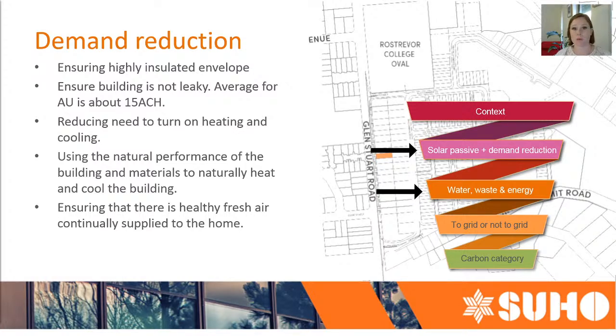If we discuss with you early on about air leakage, then we set those priorities in terms of how airtight the building is. So commonly you'll get leaking through certain parts of windows if they're not sealed correctly. Doors are a big one, garage doors, ceiling vents and so forth. So it's about having those strategies in place and making sure that your brief is very, very clear from the word go.